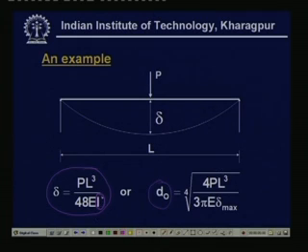Well, if it is a rectangular section, obviously the dimension or the cross sectional area of the rectangular section could be found out in a similar manner. So, you can see this particular dimension of the shaft depends upon the load, the length, the material property, and this is the delta max that you should prescribe. According to your design, you set a value of delta max, so that with all other known parameters a shaft dimension can be obtained.